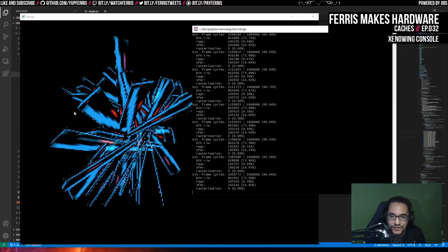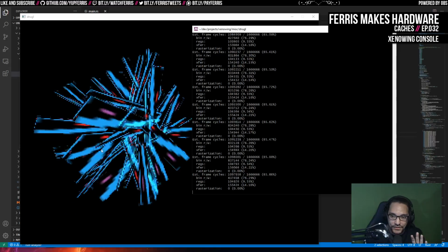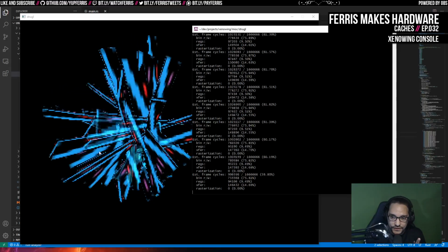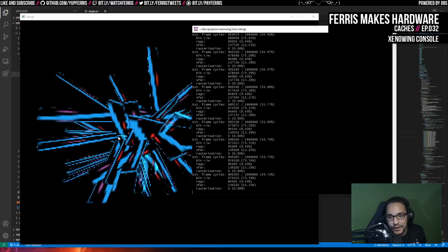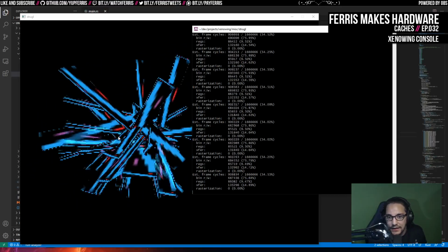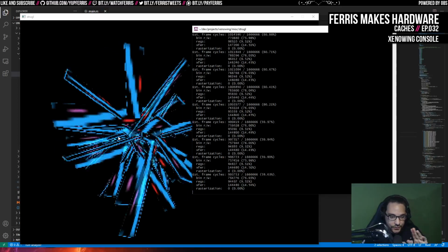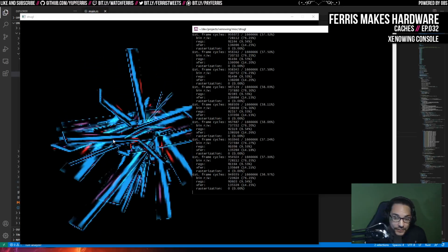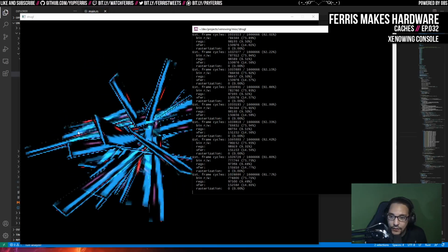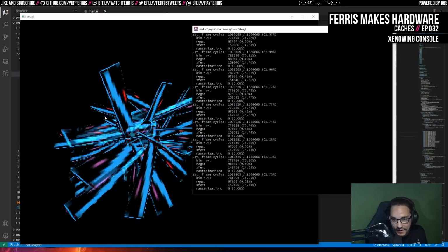And then what you do when you rasterize is you pull the pixel data and the depth data into that buffer, and then you draw the triangles, ideally at a faster rate than you would have to main memory anyway. But that may not be the case, as we'll see. And then eventually, once you're done with the tile, you ship all that memory back out. And that's a pretty good design. However, the way that I architected mine, I think there are some fatal flaws where that's not a good design choice.